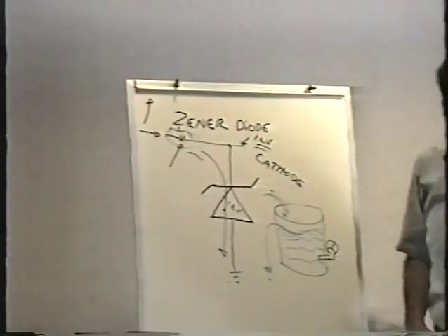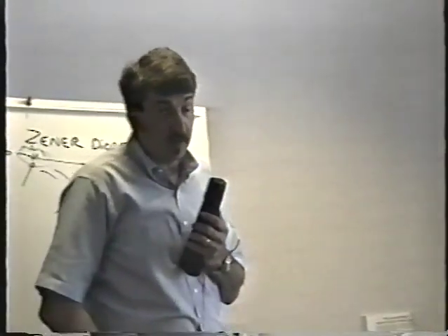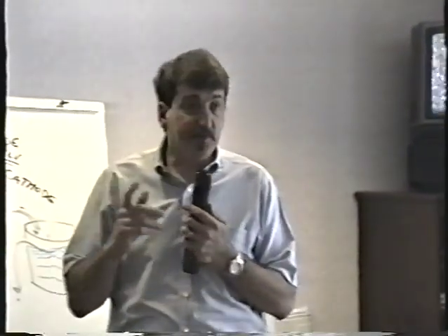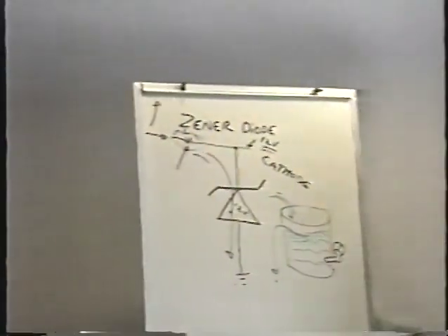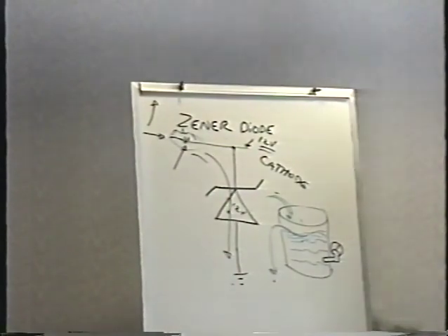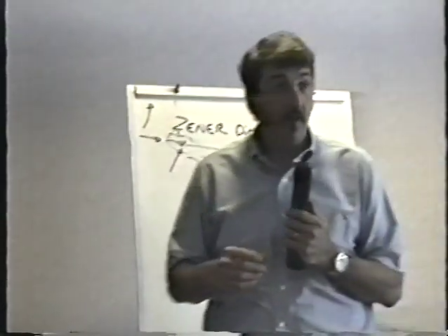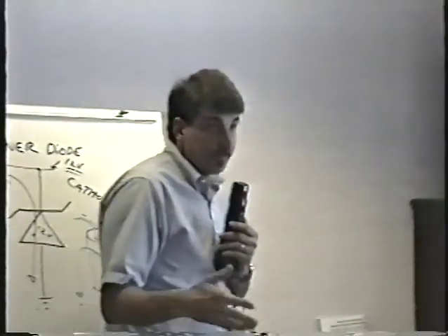Well, here's the deal. The Zener diode can mysteriously change its Zener voltage sometimes, and what it does is it drops. I've never seen it go up. It's always dropped. Here's what happens. You get to the game, in this particular case, and the score displays are not working at all. The game coins up, plays, makes all the game sounds, but just no scores. You measure the power supply voltage. We'll do this on Saturday, and you find, let's say, the minus 100 is perfect. The plus 100 is only 40 volts. Oh, well, that explains why the scores aren't working. You need 100 volts. It's only 40.